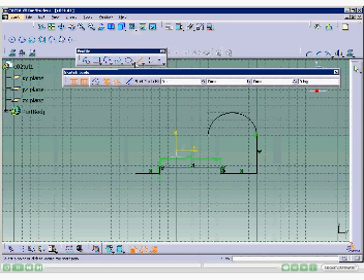Select the end point of the arc as the start point of the fourth vertical line. Move the cursor vertically downward to draw it. Click when the value of the length line is 20 mm in the Edit box of the Sketch Tools toolbar. This draws the fourth vertical line of length 20 mm. The line is no longer in the selection mode. You are prompted to enter the start point of the next line.